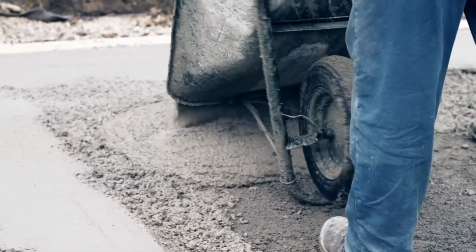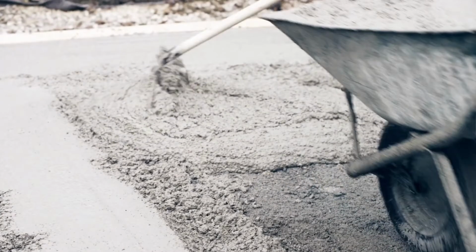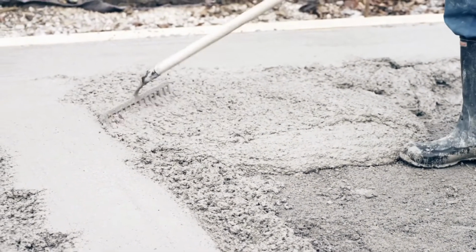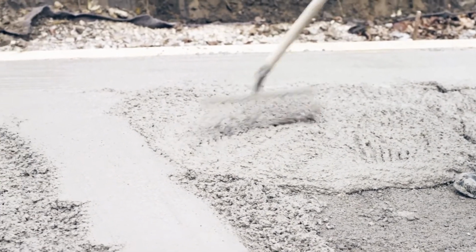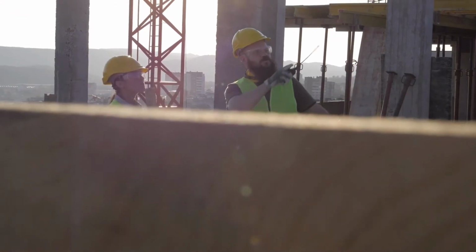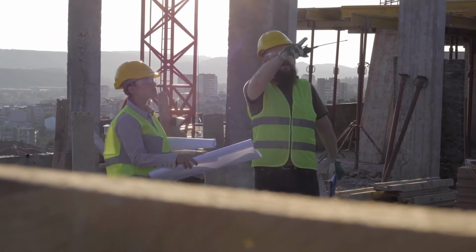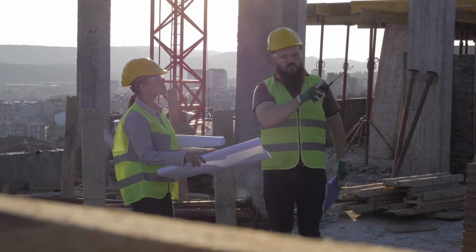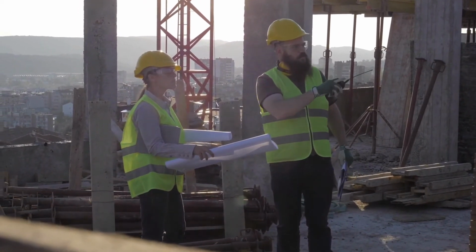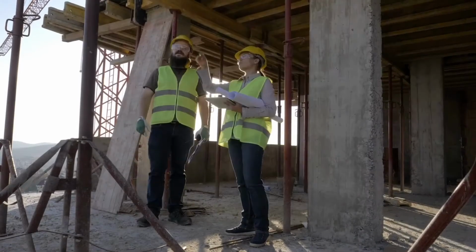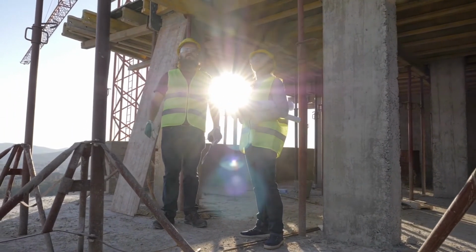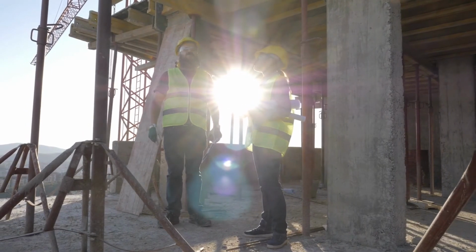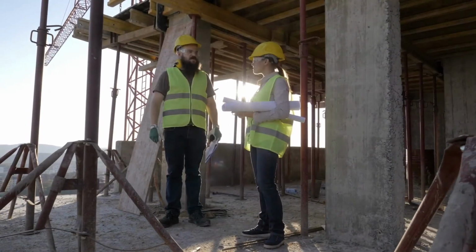This is because carbonation decreases permeability and carbonation occurs from the surface inward, creating a tighter matrix at the surface that makes it more difficult for CO2 to diffuse further into concrete. While slow, the carbonation process does result in an uptake of some of the CO2 emitted from cement manufacturing, a chemical process called calcination. Theoretically, given enough time and ideal conditions, all the CO2 emitted from calcination could be sequestered via carbonation.